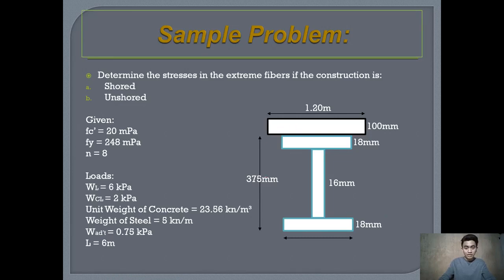So this part now is similar to your plate number 2, right? That is because the first part of our computation is for us to transform the concrete slab provided in the diagram into a steel section. Then after transforming that, utilizing again your modular ratio, which is equal to 8, which is given, transforming this one to a steel section, we are going to determine again its transformed moment of inertia.